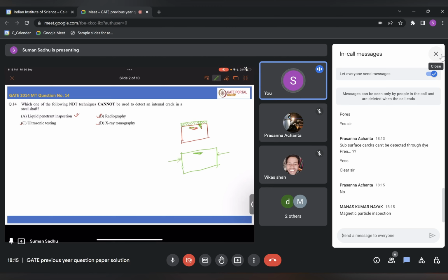The limitation is that your sample has to be a magnetic sample. In the applied field, it should convert into a magnet. So the dipoles will be arranged in the north and south direction, right? NS, NS. If your material is continuous, with no pores or cracks, then NS, NS, like this it will be arranged so that at the end you will get one side north and one side south. Yes, magnetic particle inspection.